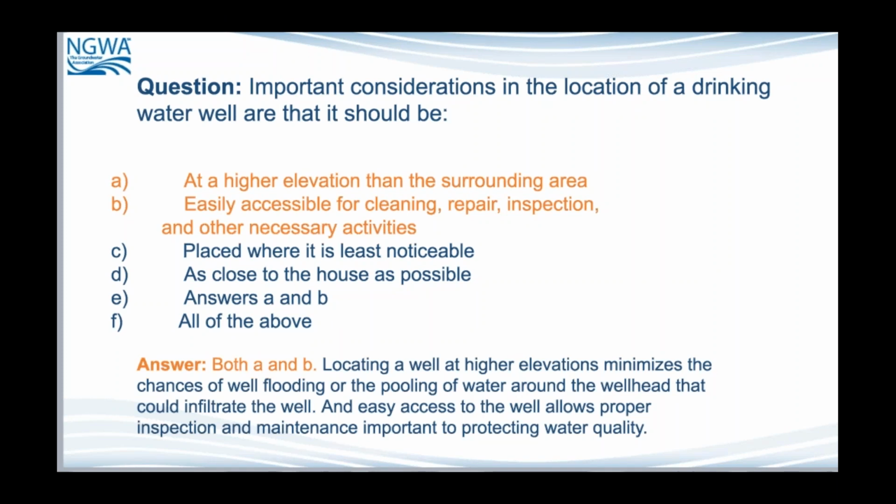A and B. Locating a well at a higher elevation minimizes the chance of flooding or pooling water around the wellhead, and easy access allows inspection, maintenance, and the protection of water quality.